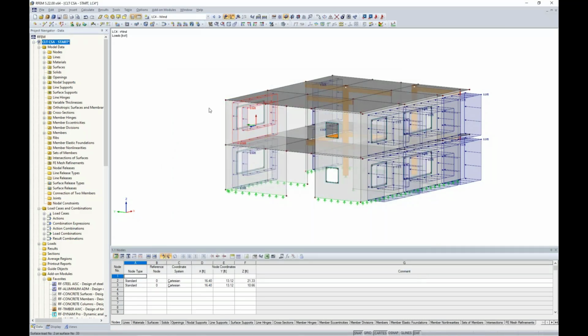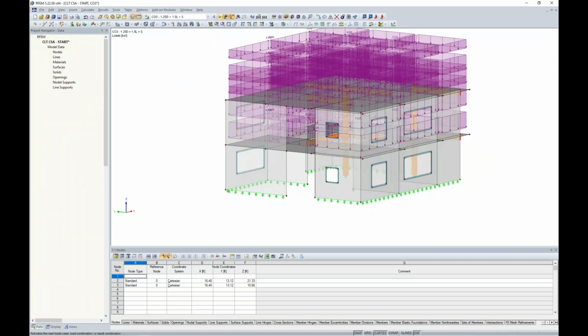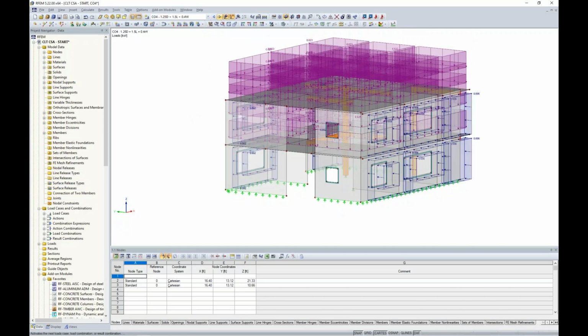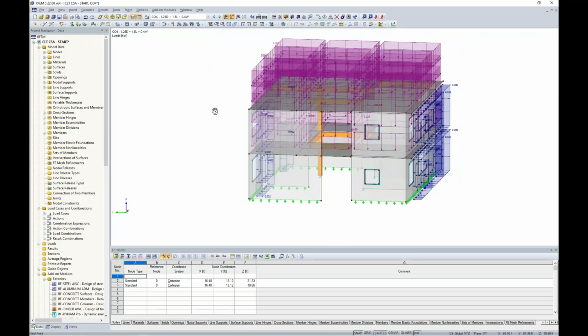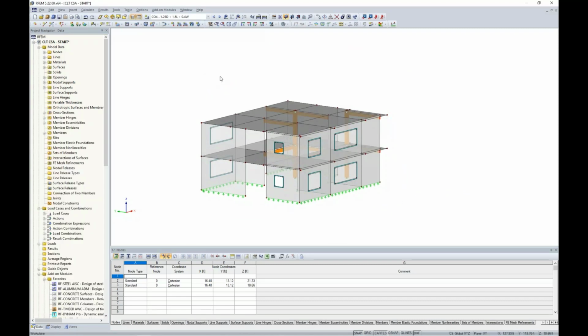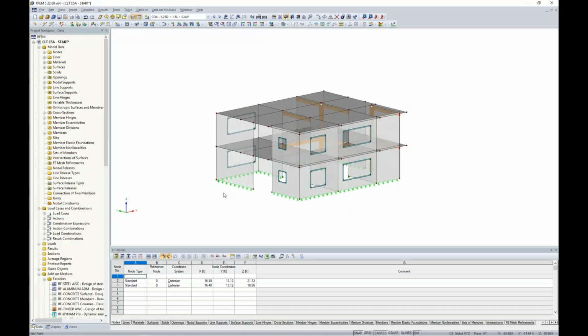So now that we have those load combinations defined, we can view them here graphically, which will include all the dead, live, wind, and snow loads shown on the structure here. And you would think that, okay, we must be fairly close to running an analysis, but remember we still have all of these concrete panels defined here rather than our true CLT panels.